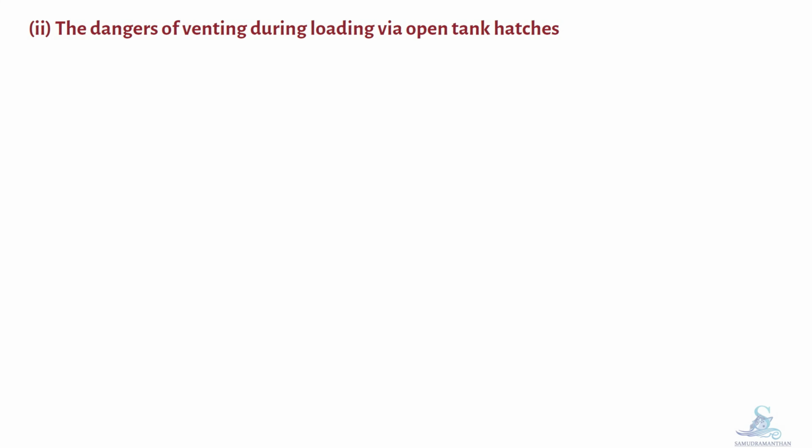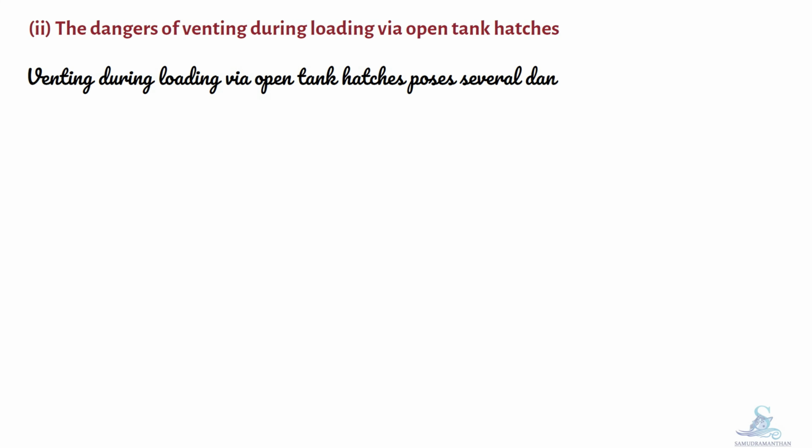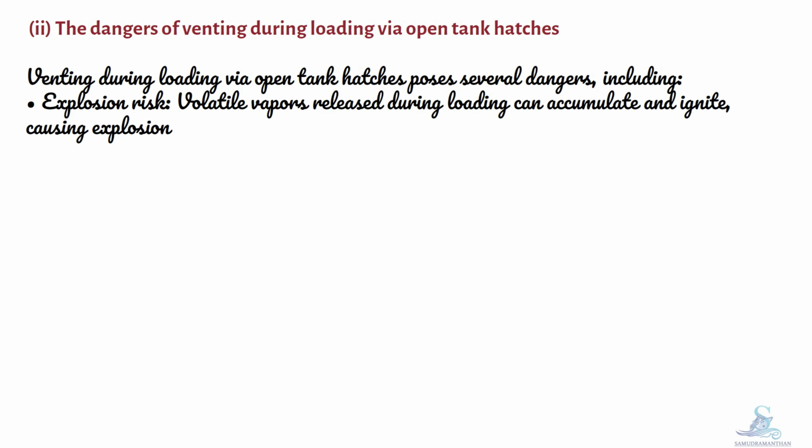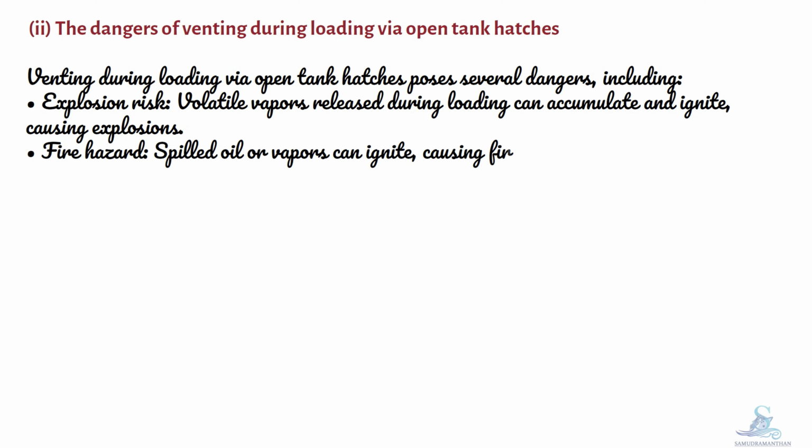Let's move to the next part of the question. The dangers of venting during loading via open tank hatches. Venting during loading via open tank hatches poses several dangers, including explosion risk. Volatile vapors released during loading can accumulate and ignite, causing explosions. Fire hazard. Spilled oil or vapors can ignite, causing fires.